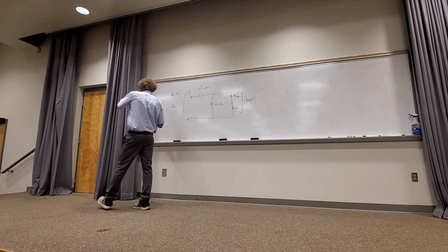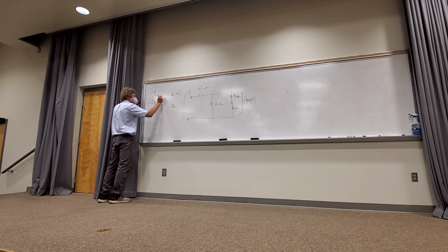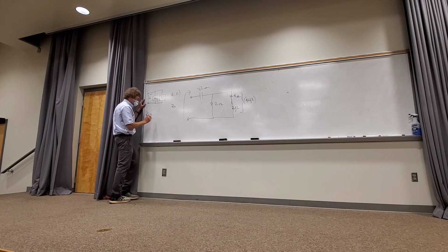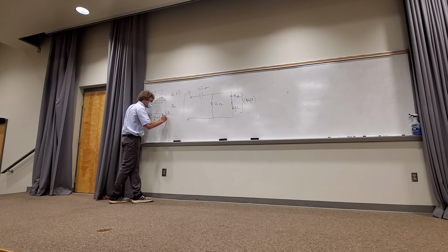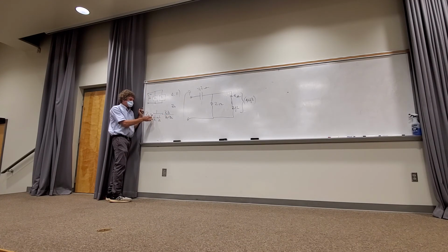And if you have two impedances, I'll call it Z1 and Z2 in parallel, and you want the parallel equivalent right here, it can be gotten as 1 over Z1 plus 1 over Z2, or it can be Z1 times Z2 over Z1 plus Z2. The second one comes from just multiplying the top and bottom of this equation by Z1, Z2. Can you all see it?